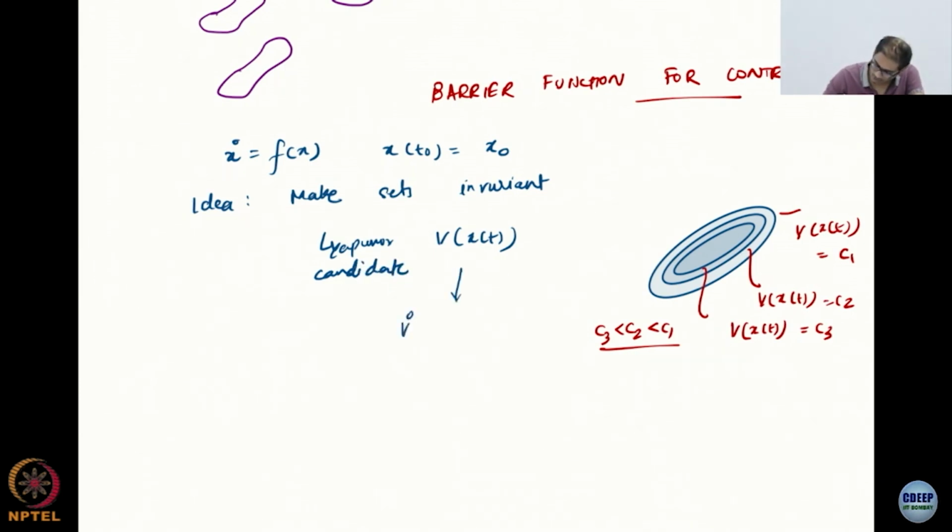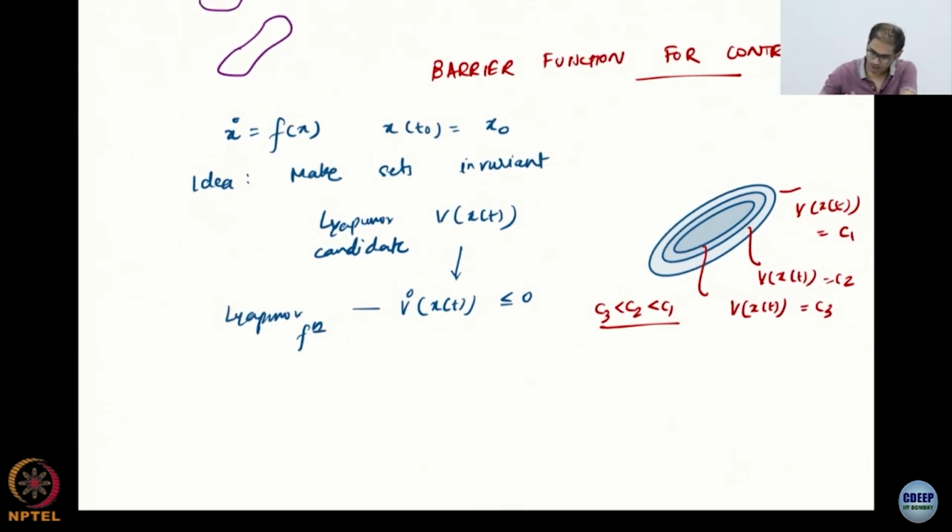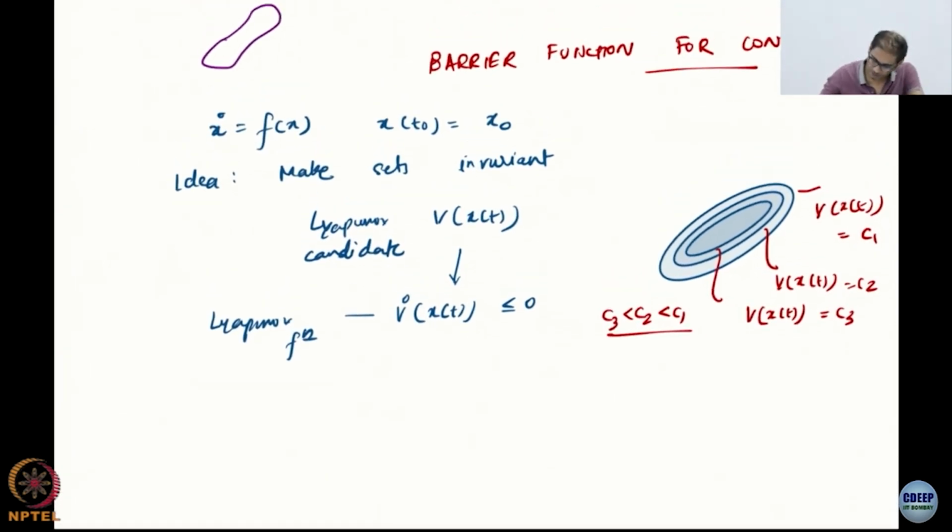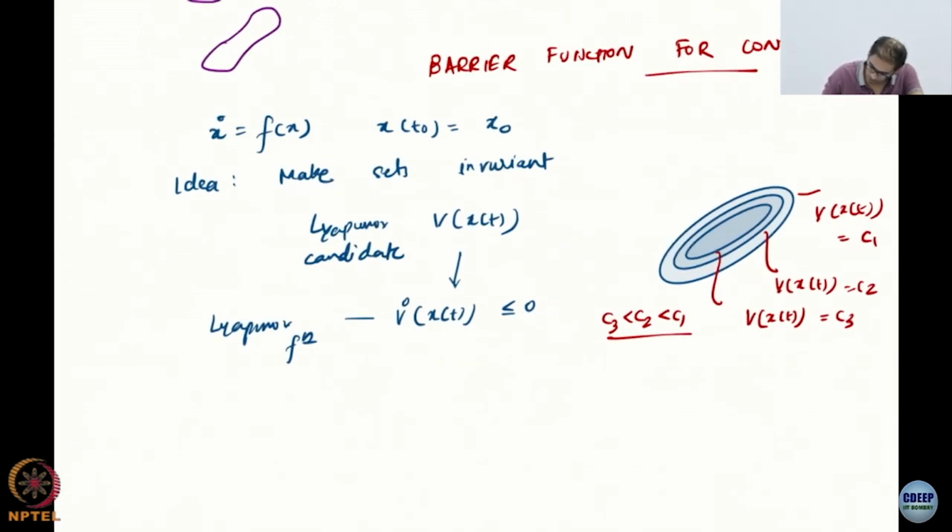We at least try to get something like V, because if we did not get this, I guess we achieved nothing, right? So obviously let us assume we got this. Therefore at this point this became a Lyapunov function itself. Okay. Now, like I showed you before, we already know that V(x(t)) less than or equal to V(x(t0)) holds, right, because of this.